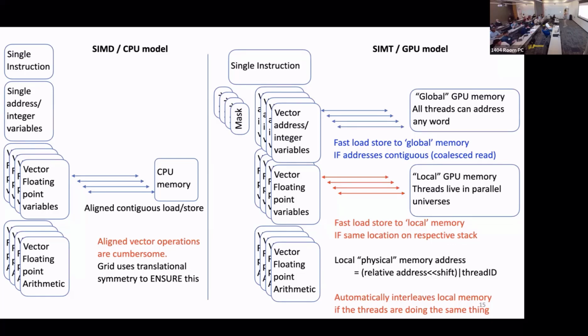So you can see that this process, by default, is a scattered load, or a gathered load, I should say. But the hardware will detect and accelerate the case where they're all hitting the same cache line address, and then they're all resolved in one cycle. That process is called read coalescing, right? Hardware detection of them all accessing consecutive data or spatially located data gets read coalescing, which goes 32 times faster than non-coalesced, right? Or that order of magnitude anyway.